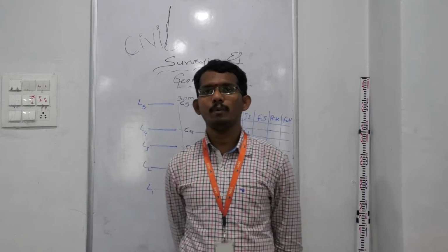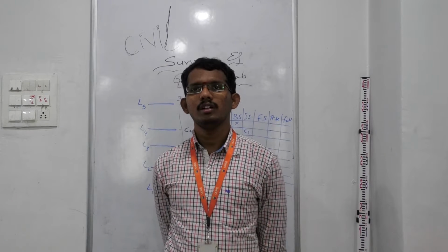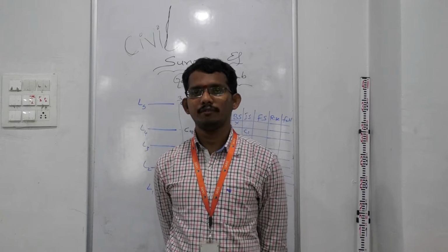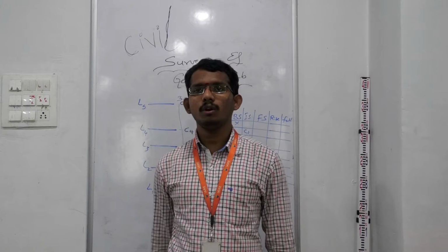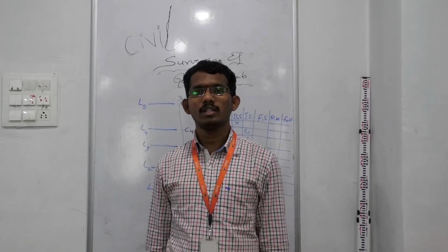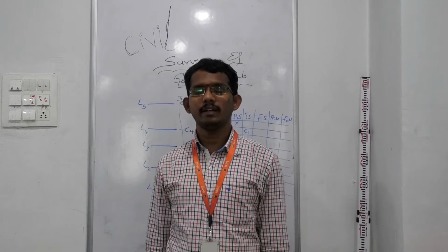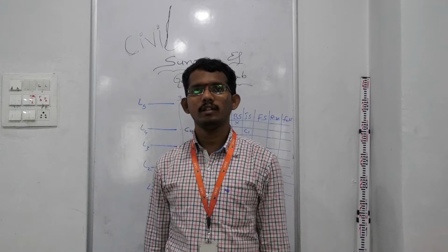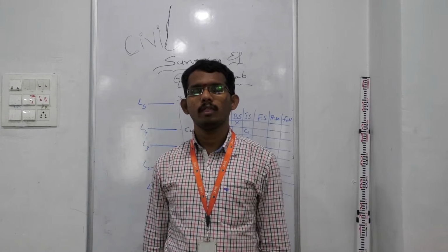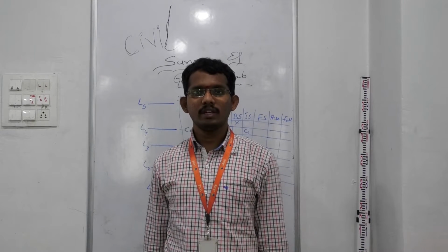Now, first of all, why do we perform this experiment? What is longitudinal section and what is a cross section? So, students, when we are plotting for a road, the length along the road is called longitudinal section, and the length perpendicular to the road is called a cross section. In surveying, a surveyor will also plot some reduced levels, some points on the ground surface. So the main theme of this experiment is to find the reduced levels on the ground points. So that is your aim.